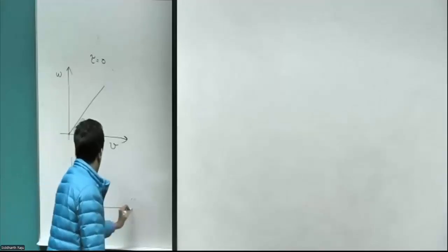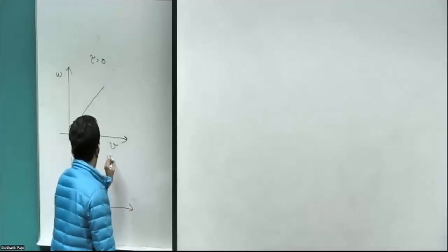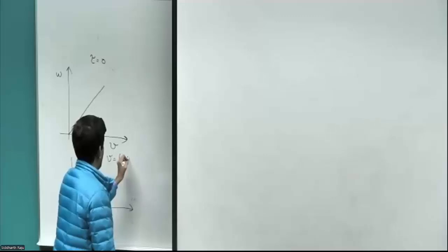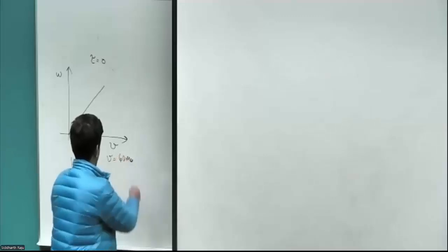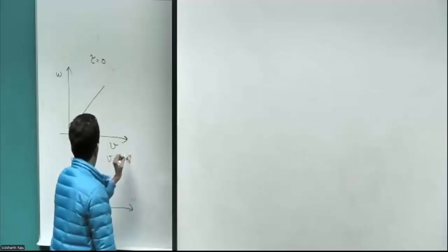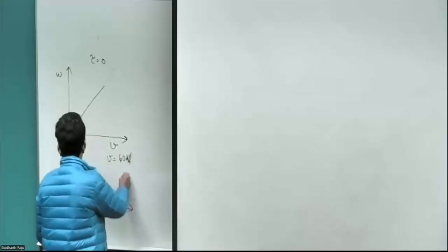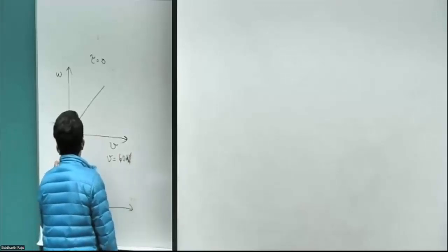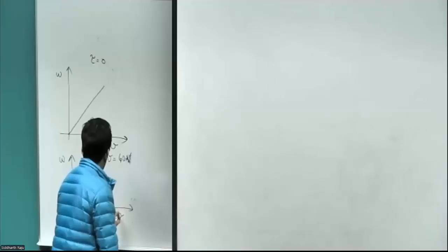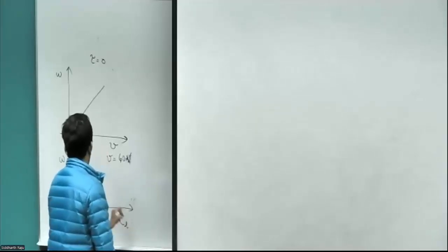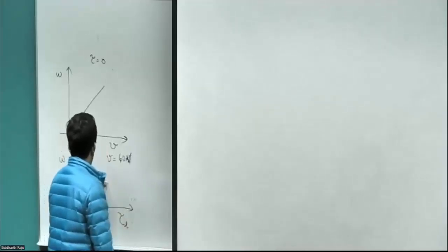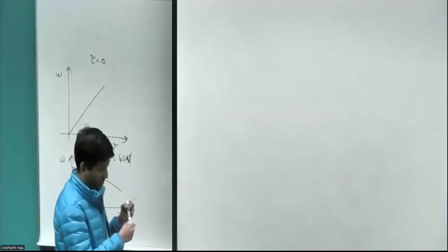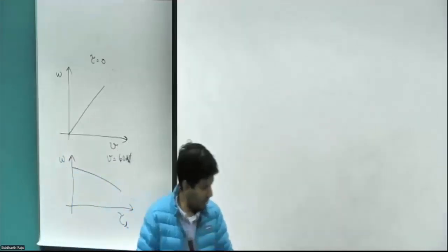And next, I'm going to keep the voltage constant at its maximum value that can be generated by the converter for a given 40 volts DC bus. Right? So we are going to retain the voltage constant. And we are going to look at what happens to the speed as we start increasing the load torque. Right? And it starts to reduce. Right? So let's look at that.